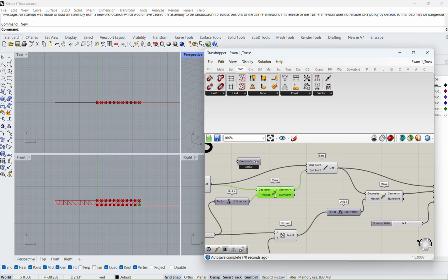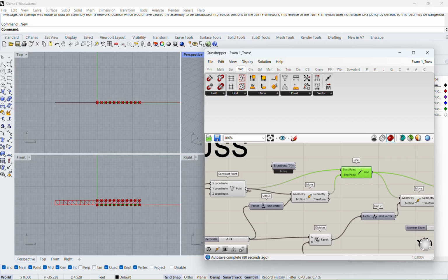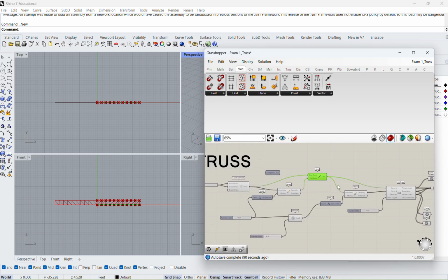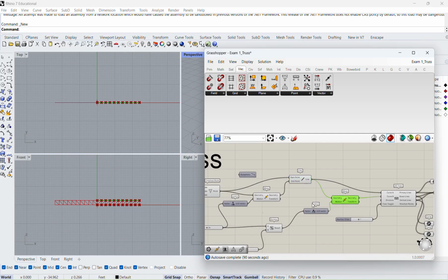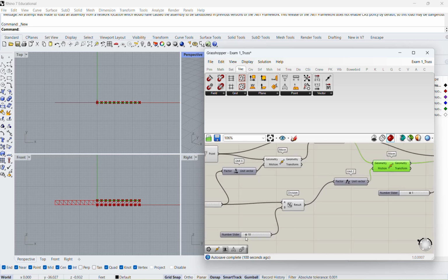All right. When you move or copy, you can draw the line, but basically it's easy. This shows the workflow: you drag in, out, drag in, so that you connect the dots. Once you draw the line at the bottom, you copy the line in the vertical Z direction by some feet, which in this example is 2.4 feet.